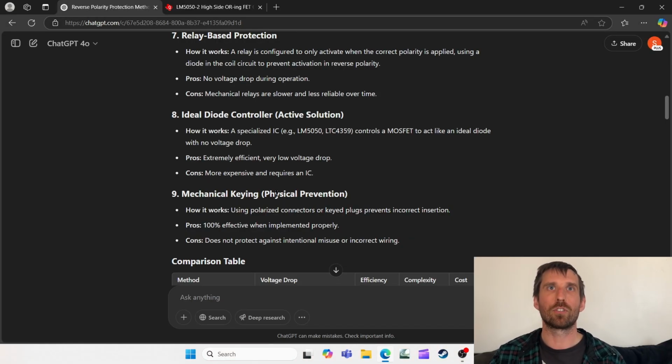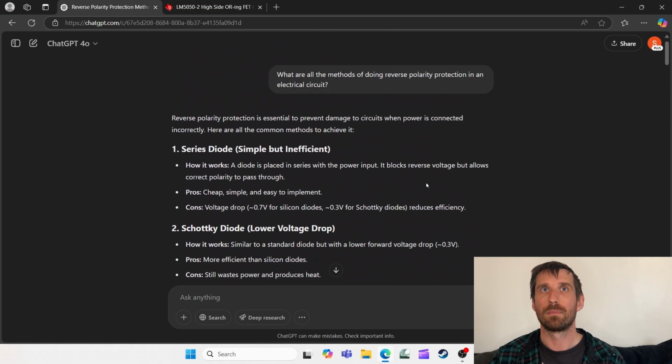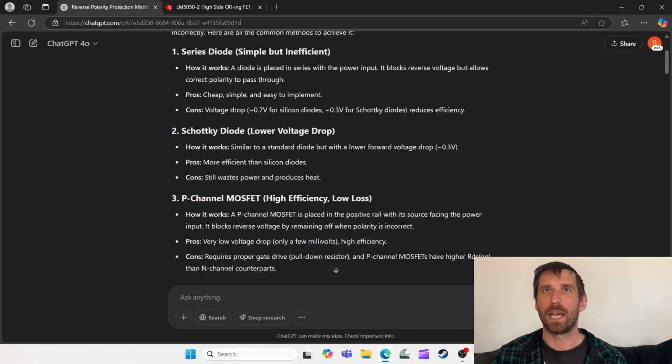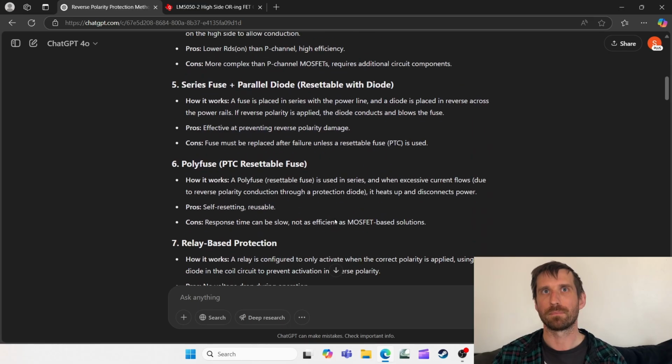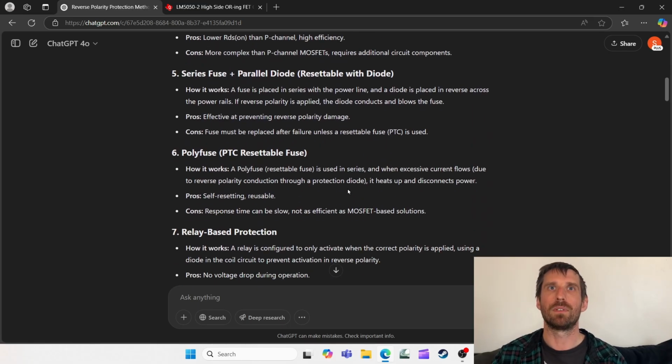So ideally, out of this whole list, this should be number one. If you can do this, you can be home free and not have to worry about circuitry. But when you do, I like mechanical keying, ideally. Diodes for low current, everything else P-channel. That's how I do things in the real world. These other ones, some of them I have done or thought about, but they're not as good.